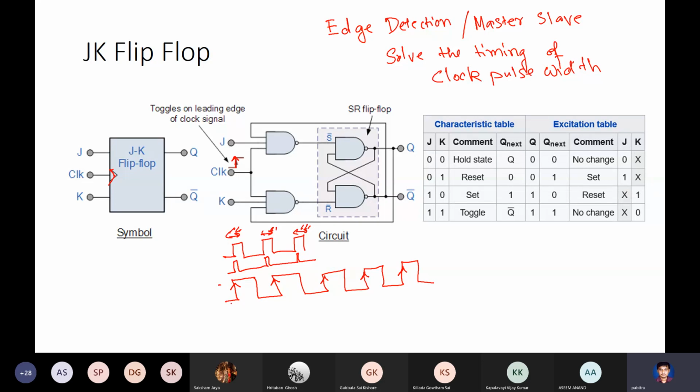Okay, so the latch can change, will consider the input, whatever is the value of this input in this snapshot of time. And the output also will change only at these events. What is this event? Up edge event, sometimes called a leading edge event. Only at this leading edge event, only the event, what is the event? Event is clock going up, only that moment of time.